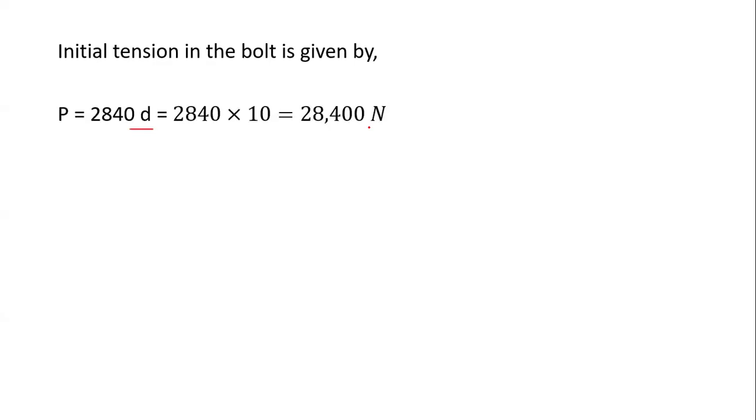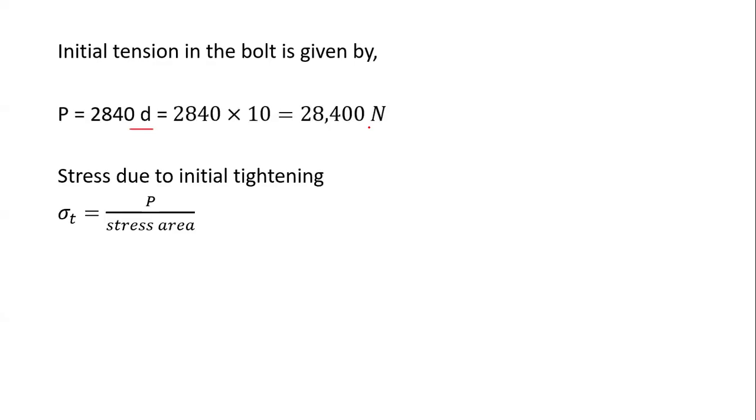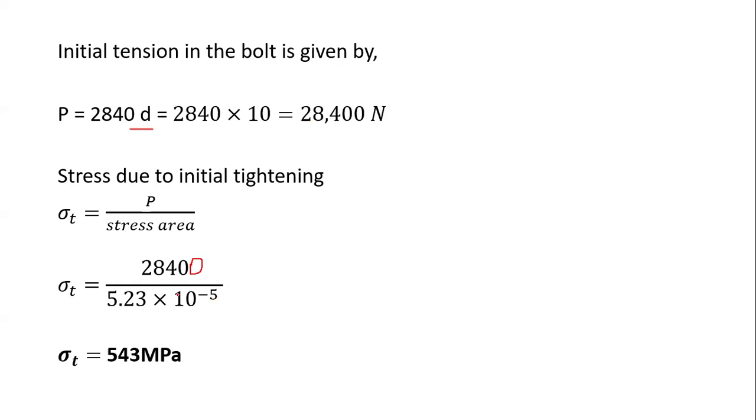So with that, we now proceed and just say tensile stress is force over area. So we bring this number on top and then the area below. So here we have 28,400 divided by 5.23 by 10 power negative 5. And then the tensile stress becomes 543 megapascals.